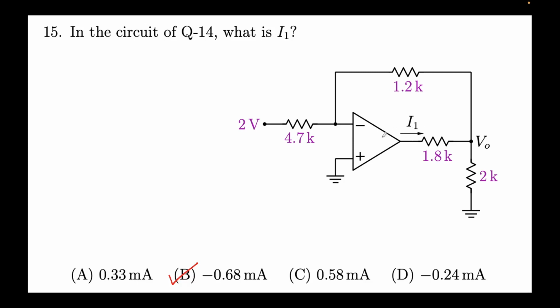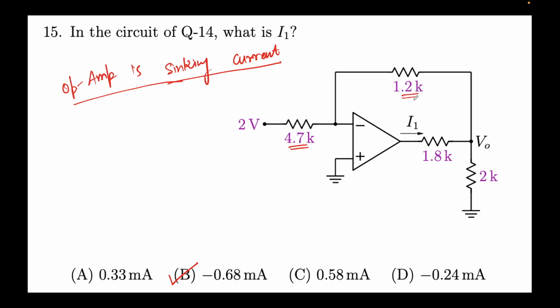So what we can conclude from that is that the op amp is sinking current, right? This op amp is sinking the current because this current is negative. This means current is flowing in this direction. What it would effectively mean is that whatever current is being provided through this branch, only a small fraction will be going to the output. That happens because of the way you want to drive the load, and it also depends on all these resistances. The key takeaway is that you can tweak the current flowing through the operational amplifier just by tweaking this voltage.